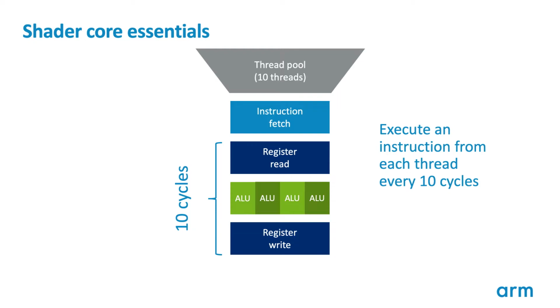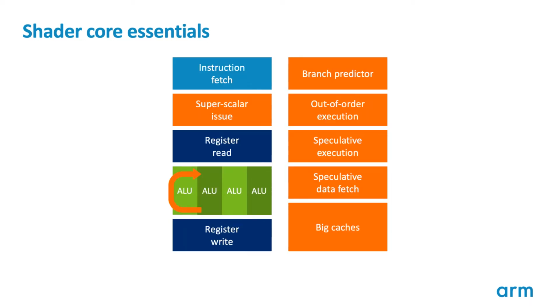to fill the pipeline. This increases the latency to complete a single thread by a factor of 10, as it only gets to use 1/10 of the performance at a time, but the overall throughput of one instruction per cycle is maintained. This change has multiple immediate advantages. Firstly, we no longer need special issue logic and speculation to find parallelism in the instruction stream of a single thread. We have parallelism inherent in the problem, and can instead fill parallel units by issuing instructions from multiple threads.